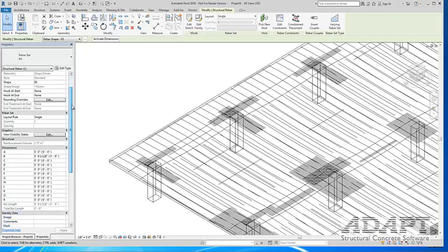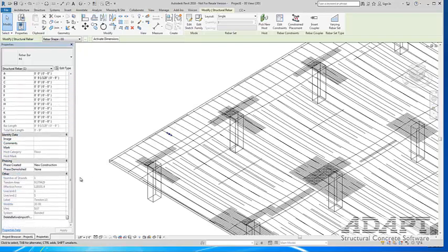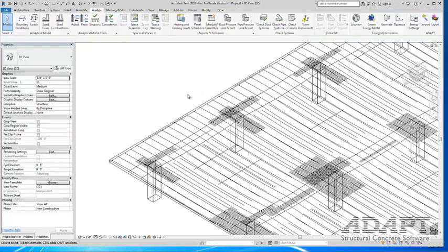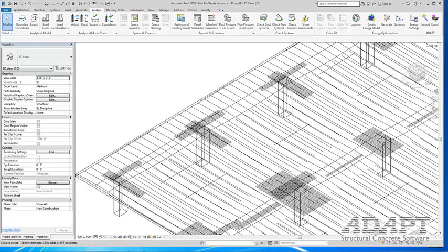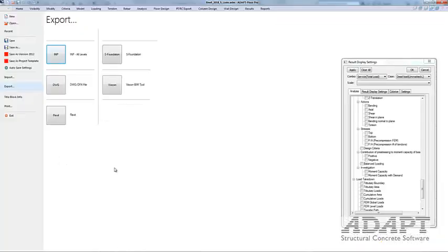segment and I scroll to the bottom, this segment actually has properties associated with it. So we tag, for example, a number of strands, tendon area, effective force, live and dead, the tendon label, wobble, and the type of post-tensioning system that it is. And these can then be used within Revit to manipulate data and to represent the tendons with tags for the drawing production.